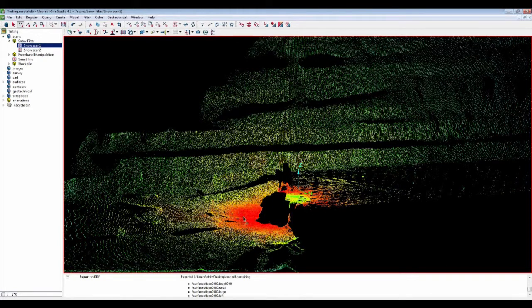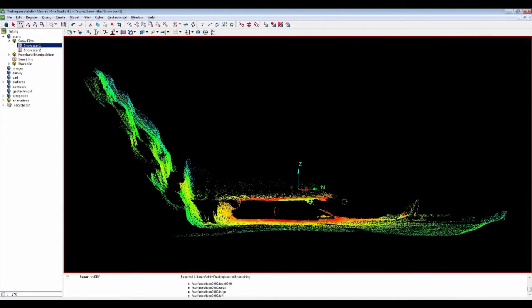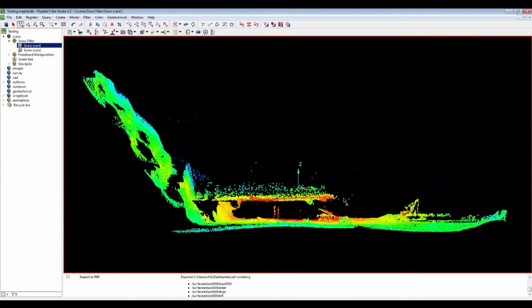But we're not out of the woods yet. If I put this horizontally, and I'm going to use the plus button on my keyboard to increase the pixel size just so everyone can see what I'm talking about here, there's still some points that it didn't get. Obviously, we went from thousands down to a handful, maybe 20 or 30. And it's really easy to rely pretty heavily on the despike option with the triangulation, and in this case it might get rid of all of these, it might not.